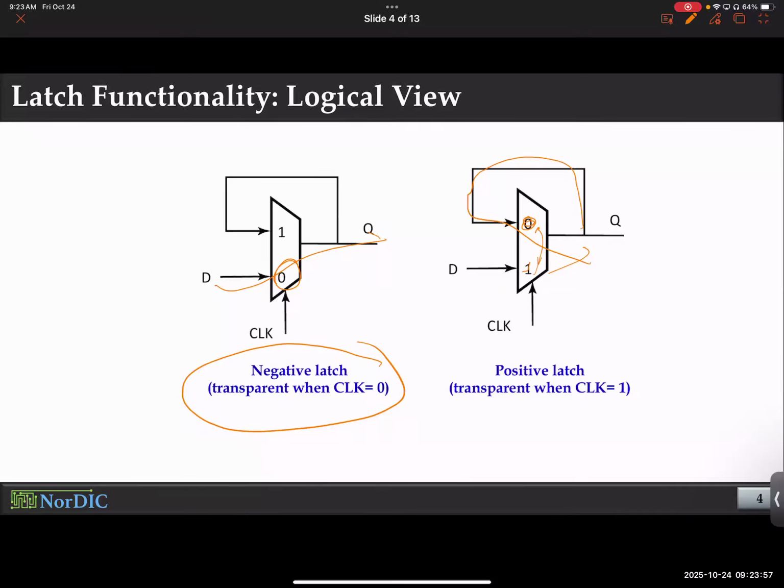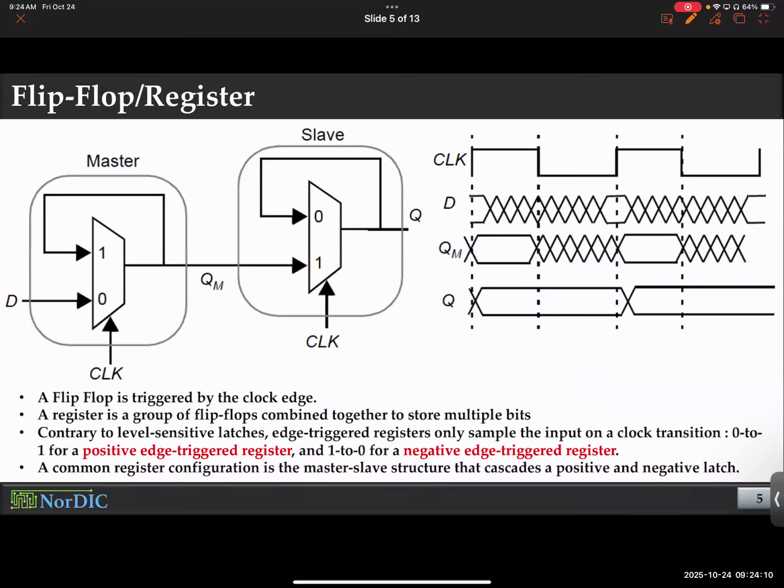So this slide is supposed to show you the simplicity and the subtle change that turns a combinational circuit, essentially a mux, into a sequential circuit through feedback. All right, now we're going to take it one step further. So far, whatever we've seen are all latch blocks. What a latch does is it basically holds on to the output. That's why there is a mode called hold mode. It is holding the output.